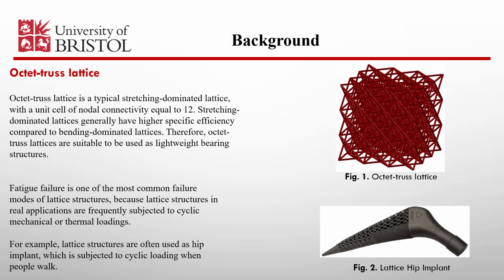Literatures concluded that stretching-dominated lattices generally have higher specific efficiency compared to bending-dominated lattices. Therefore, stretching-dominated lattices are more suitable to be used as lightweight bearing structures, and bending-dominated lattices are more widely used in energy-absorbing